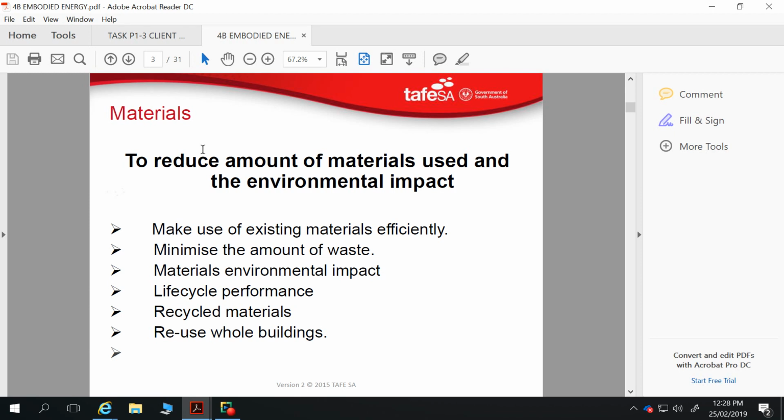Now all those defects, when a piece of timber has been cut down and milled and dried, and then you buy it from the timber supplier, it's already gone through somebody checking that piece of timber over and stress grading. You've got that. Yeah, you've got that. When you're buying timber that's from an old building that you've pulled out, you've got no idea of the provenance or the stress grading of that, and that comes down to you to make that decision, or you get someone else to stress grade it.